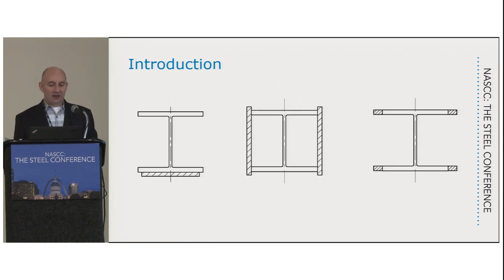The one in the middle, obviously that's going to be good for torsion because it makes a closed shape out of the wide flange, but it also increases the weak axis properties for weak axis buckling a significant amount. The problem is that you always have something framing into the web there, and in the structures that I typically work on, industrial structures, you're also going to have vertical bracing gusset plates to contend with. So you might have to cut those significantly short. I'm not saying that you wouldn't have to do that for the flange plates either, but just keep that in mind, especially if you're going for torsional stiffness there. You're going to have a very stiff torsional section, and then when you cut it back, you're going to go to a very non-stiff torsional section.